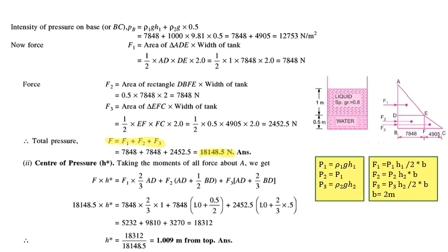Now in order to calculate the center of pressure, we have to take moment of all the forces about one point. It could either be about the base or it could be at the water surface. So here we are taking moment about point A, that is the liquid surface.